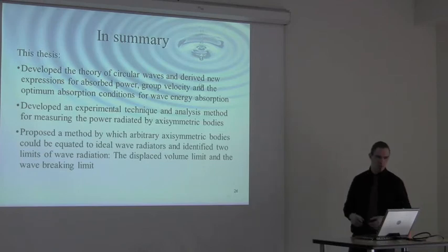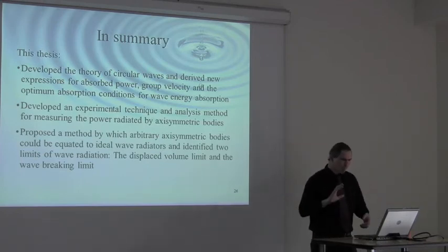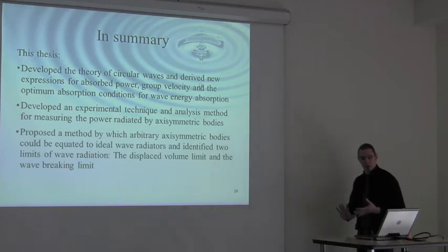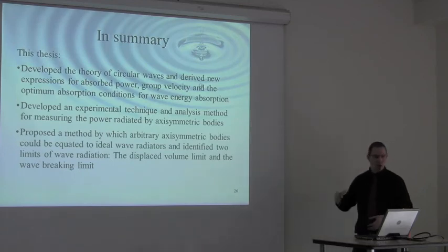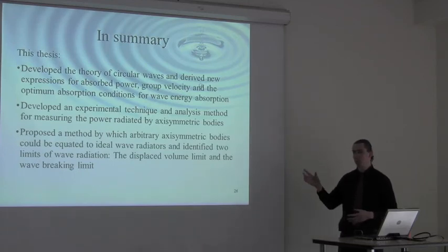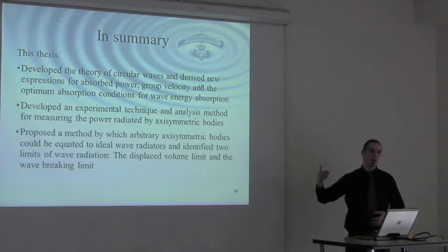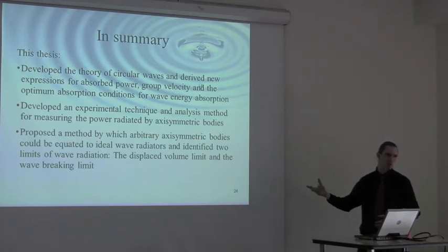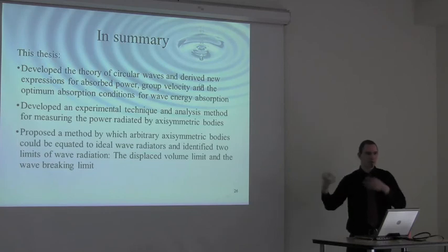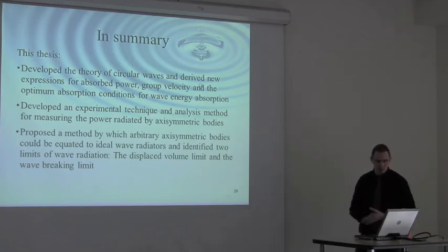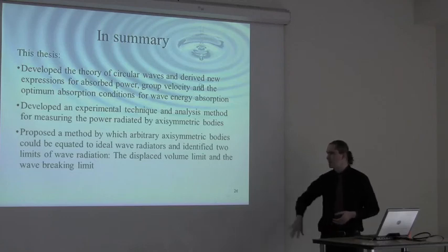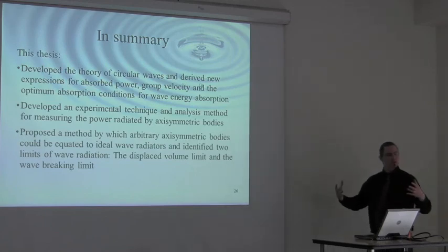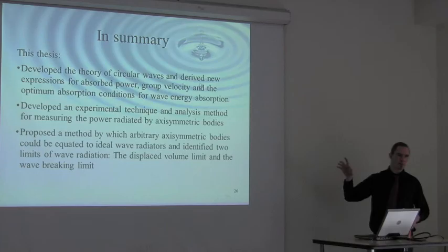So this just looks at the wave radiation side of things. The experimental technique and analysis method work quite well for matching and recording waves. There's still plenty of work to be done there. There's a lot of data that I've recorded that hasn't been looked at, which I did compound motions, so sort of surging and heave together. Preliminary results are, it looks like that you just sum the two of the individual cases, and that's about what you get in terms of radiated wave. That's just preliminary. Still a lot of work to be done there. And the method I've proposed of creating this characteristic cylinder or an ideal radiator as a benchmark for the peak efficiency